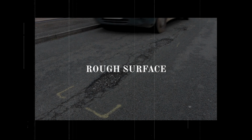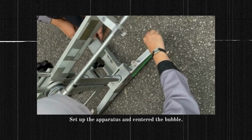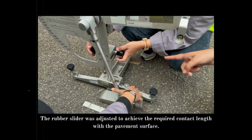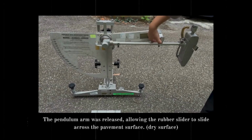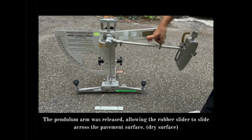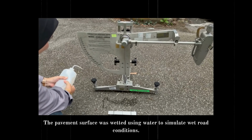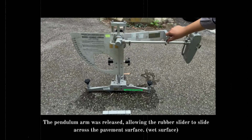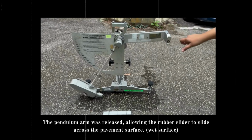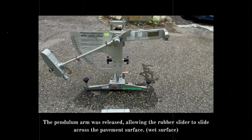Rough surface. 1. Set up the apparatus and center the bubble. 2. The rubber slider was adjusted to achieve the required contact length with the pavement surface. 3. The pendulum arm was released, allowing the rubber slider to slide across the pavement surface. 4. The pavement surface was wetted using water to simulate wet road conditions. 5. The pendulum arm was released again, allowing the rubber slider to slide across the wet pavement surface.